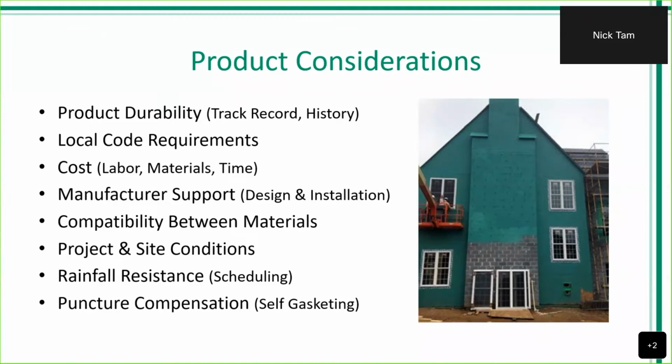For rainfall resistance, there are materials that may require a few days of no rain to make sure that it does not hinder its curing ability, especially when we talk about fluid applied membranes. Also, you want to make sure that the substrate is not wet when installing any sheet applied material.